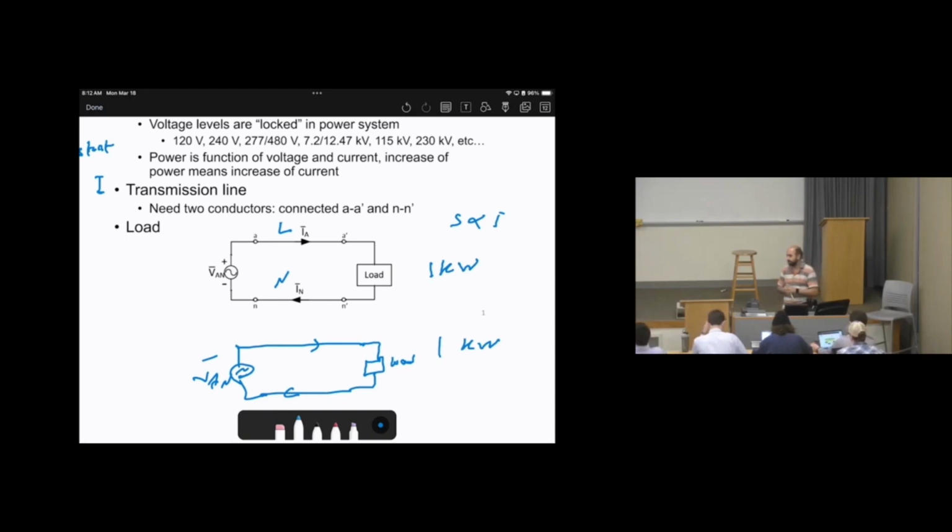So yes, increase the wire diameter. That's another approach. Again, you can imagine this as supplying your home with water when you have a large demand: one way is connecting a new water line, or increasing the diameter of the water pipelines connected to your home. Economically, removing the existing one and adding a new one with a larger diameter might be expensive.